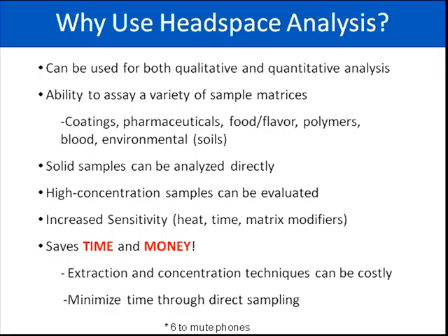It enables us to look at high concentration samples. In the case of a purge and trap, you're pretty much limited to the ppb level. When you get into static headspace analysis, you're only sampling the gas. You're only sampling the headspace above the sample, so it's a very clean analysis. So in cases, you may end up being in the very high ppm range.